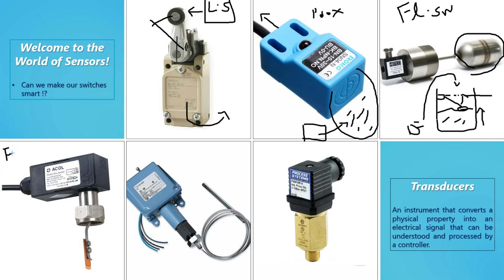This is a flow switch, right? In industrial processes, there are a lot of pipes carrying the process fluids across the whole plant, right? So if you install a device like this on a pipe, it can detect a flow. For example, the flow of fluid carries a force, right? And when this force impacts this sensor plate here, it tries to bend it, and inside there is a mechanism that will trigger a signal according to your requirement. These are known as flow switches.